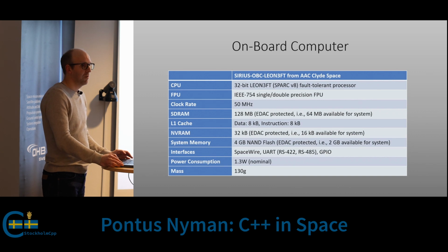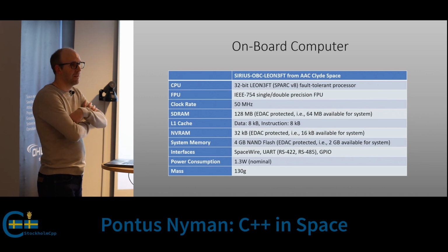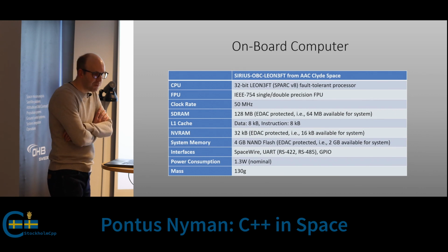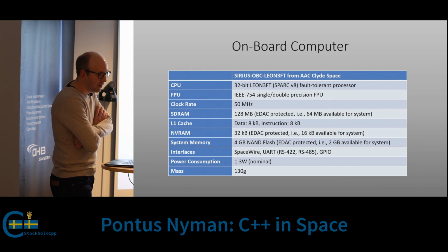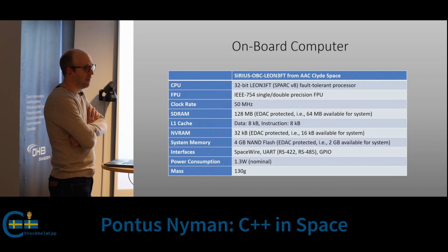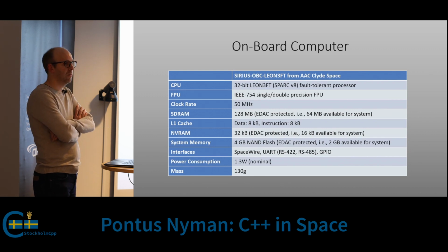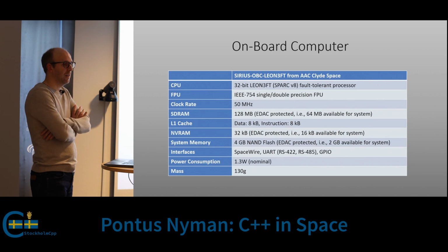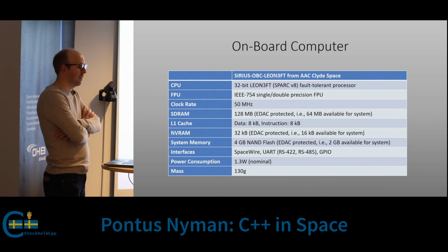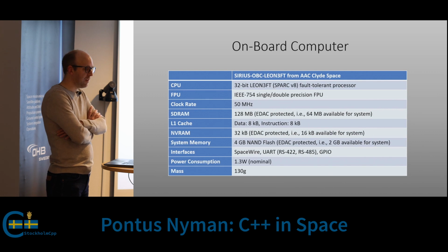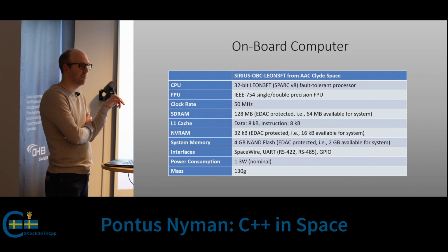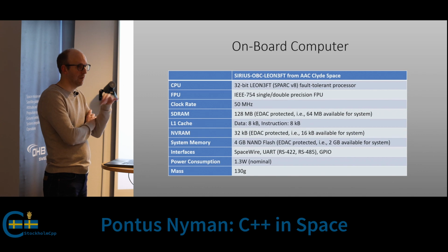You correct also, but you can only correct a certain number of bits. If you get too many errors, you can't do anything. And if you get a bit flip in the memory areas where you actually have instructions, I'm not sure about this, then I think it will do a reboot just for safety, if it can't fix it.